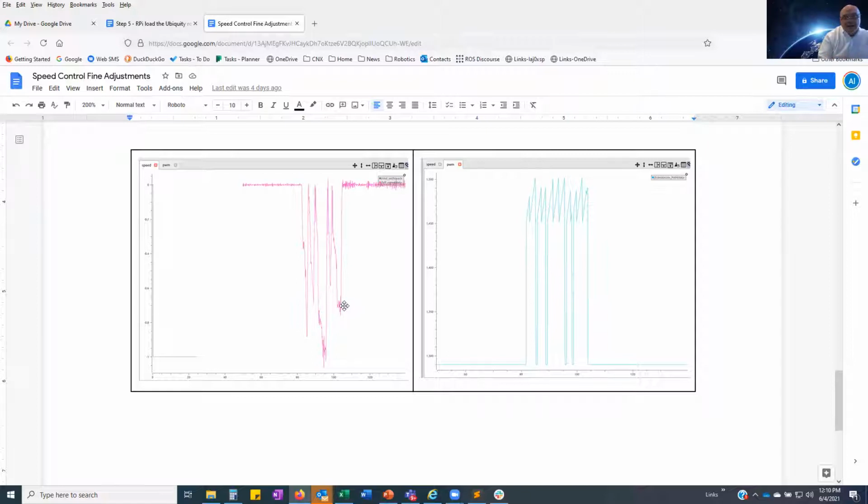I don't have it handy, but I have done that in the past. I can do it again just to revalidate that they're basically in the same ballpark. And that's good that you have the two sources, because you can directly compare the two and say, is it showing me a constant speed when I'm moving at a constant speed? If not, then you've got something wrong with your wheel speed sensor, or the code that's running it. So that would be a good thing to do.